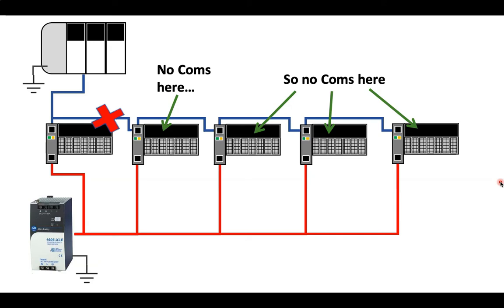If a module on a field network is not communicating on a serial-based network, the approach can be: check power, look at the status LED to see if the slaves can see the master, and check on the master's LEDs or LCD to see if there are slaves that the master does not see. Also, you can verify the network cable as well. These are just a few points, and you can add to these based on your experience.